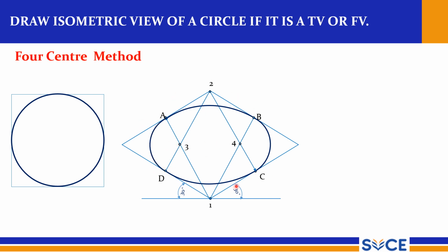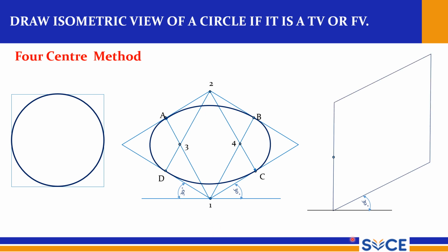So how easily you can draw this, right? So this gives you a perfect ellipse, and also the curve will be very smooth since you are using compass. So this is your horizontal circle, right? Horizontal circle, and this is vertical circle. This is vertical circle, same procedure.